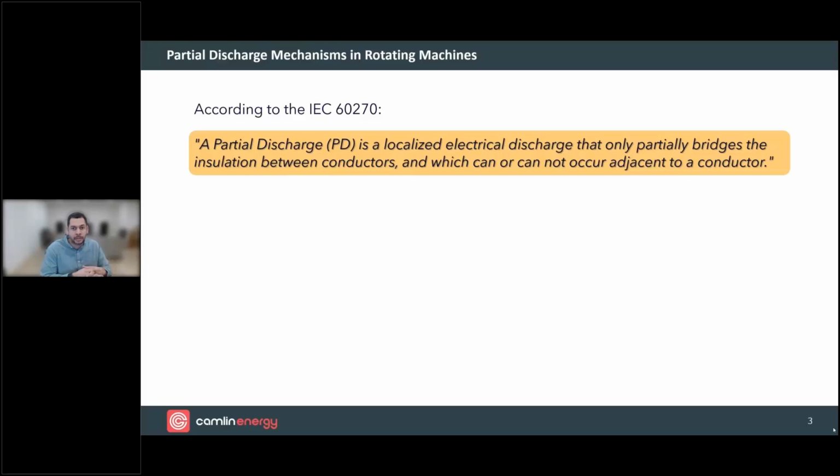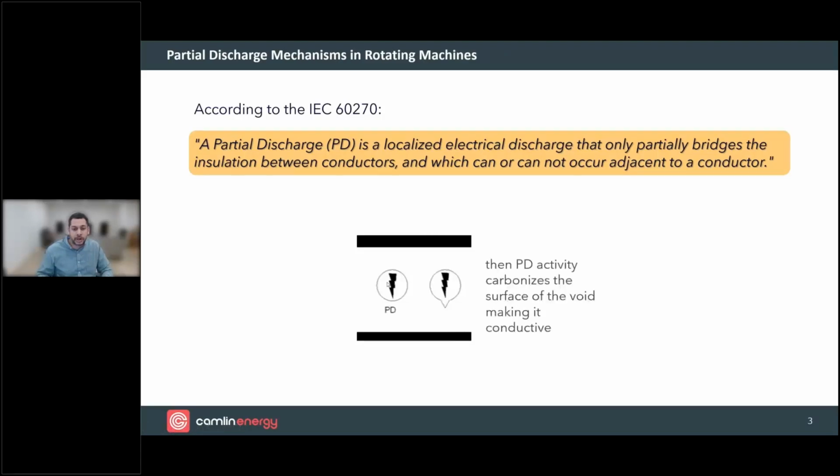Okay, so considering the more traditional electrical discharge starting as maybe a void. If you have high voltage up at one of these terminals here at the top on the black bar, and then the other conductor is either an opposite polarity voltage or a lower voltage or ground. If we have a void within the material, because it has a lower permittivity than the surrounding material, it's going to have higher electric field stresses at that location. And discharges can start in this void, and the energy created by the discharges creates some byproducts.